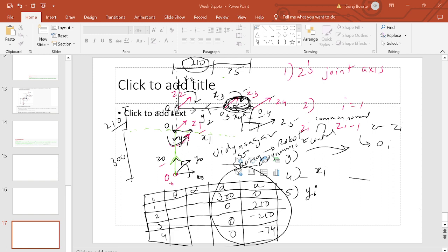So if the end effector position is at the origin and you have equal length links, infinite solutions are possible. If your second link is short, you cannot reach that position. If your first link is big and the second link is only this much, you cannot reach the origin. But if you have equal length links, then it can completely overlap and approach from the entire 360 degrees, and then infinite solutions are possible.